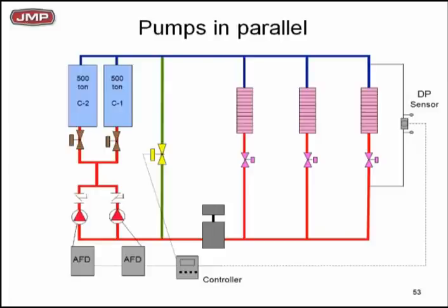Here's a primary pump loop, and you see a little green pipe. But you need to understand primary, secondary pumping, how this works. One set of pumps, pumping everything. Yes, you got a green pipe, but remember the common pipe and the primary, secondary theory. We remember if we put pressure drop in the common pipe, we force circulation in the secondary. That's all we're doing here. We get a little bypass, a green common pipe with a valve in it deliberately, that we're throttling to control the flow rates through the chillers and through the system, primary pump.